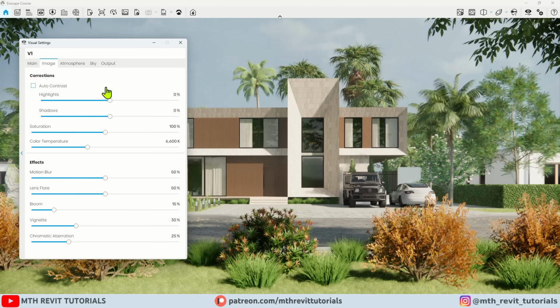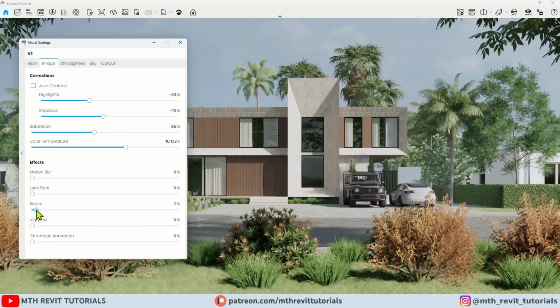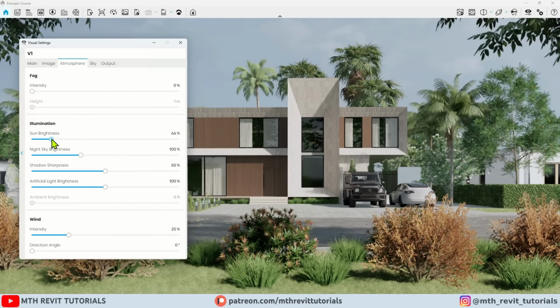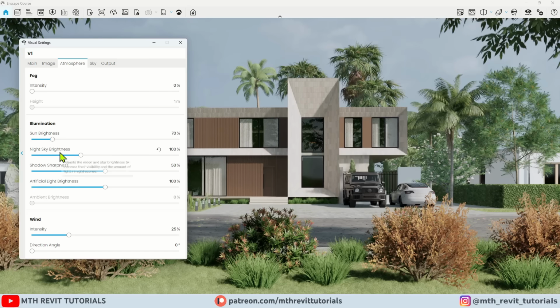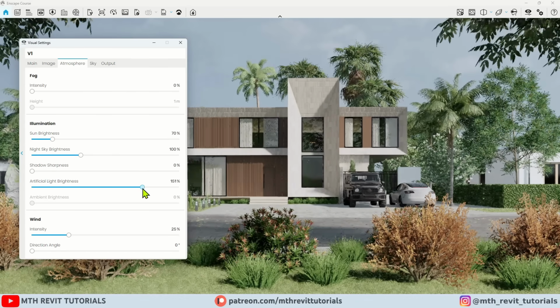In the image tab, I'm going to lower down highlights and shadows a little bit, and saturation as well. You can adjust the color tone here as well. I will remove all these effects and leave the bloom at around 5%. In the atmosphere tab, I'm going to remove fog and lower down the sun brightness. Remove shadow sharpness and increase the artificial light brightness to match the scene.